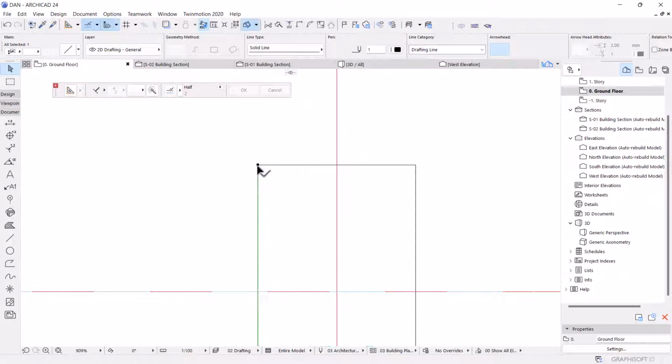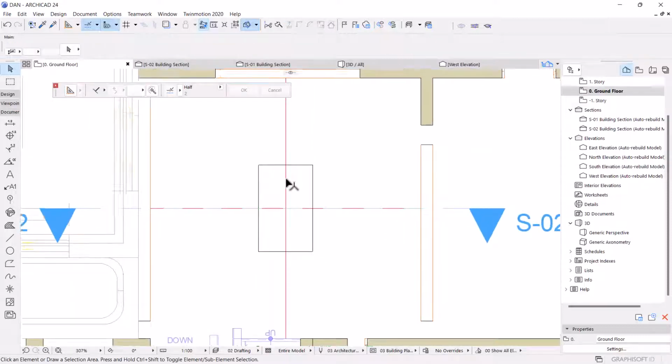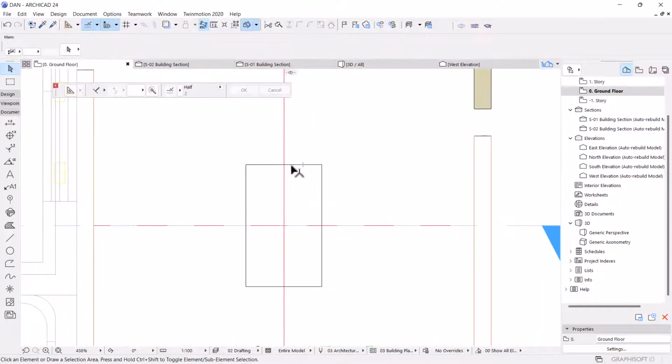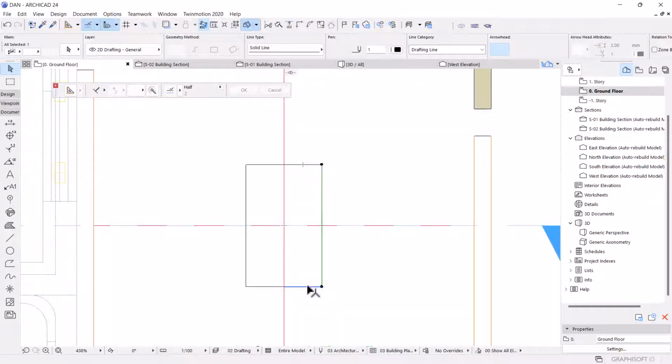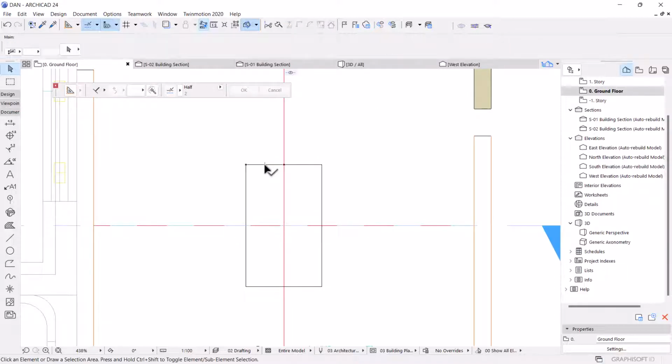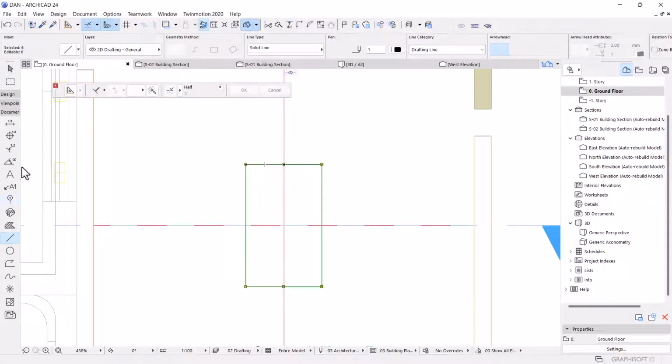So for me, when it comes to lights, I mostly use the morph tool and the slab tool to draw them, sometimes the shell tool as well. So this is the basic thing that we want right now. We have it now, so I click everything and I want to group it, so Ctrl G, and I select it. I click on the line tool, then you come to this, I think you remember it, the control box. We just want to offset the elements.